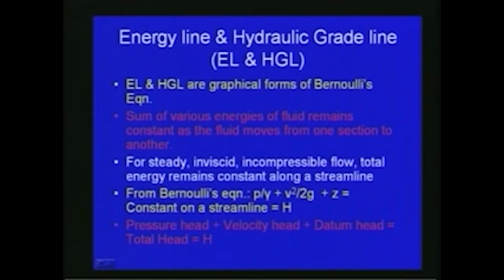So before going further with the derivation of other fundamental and momentum equations, we will just see some aspects of the total energy, and then with respect to this, the hydraulic grade line and the energy line. We have already seen with respect to the Bernoulli's equation that total head is equal to the pressure head plus velocity head plus datum head. The total energy will be, of course there will be losses also, and the internal energy will also be there. So that also we have to consider, and that is the total energy.